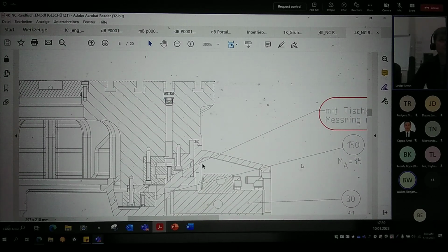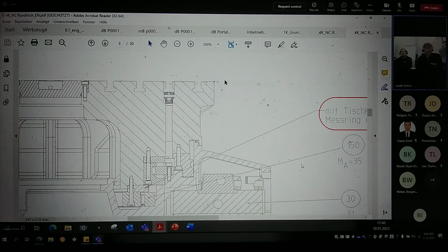I think so. Yeah. We see here the bearing connection, and if you measure the runout out of tolerance, the tolerance here is described sometimes as 16 microns or 20 microns, but from experience, don't go over 10 microns runout on the dual block machines.